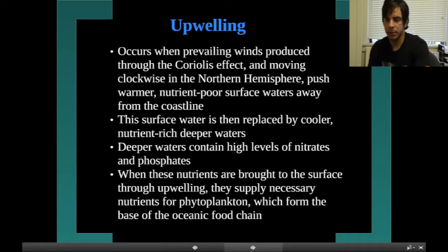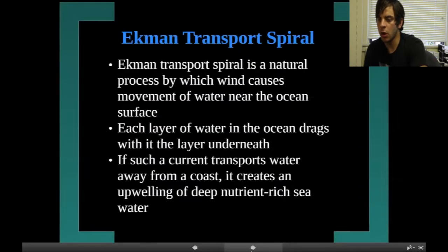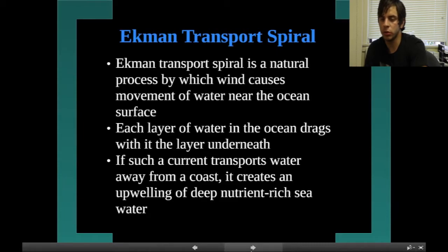Advantages of drip irrigation. Drip irrigation is the most efficient type of irrigation. Why? One, because it has increased efficiency. Almost all water reaches crops, with no runoff. 2. Less energy is required. Lower water demand results in lower pumping costs. 3. Lower demand on aquifers or depleted water resources.